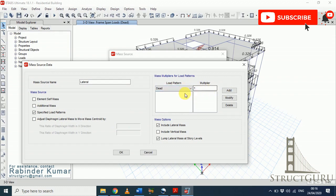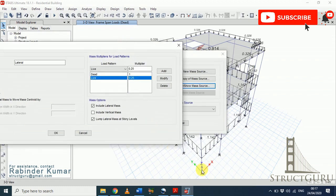So we have to include all the dead loads of the building. Select Dead from this option and click Add, and for 25% of the live load, write 0.25 and click Add. So we are done. Now there are 3 other options, so let me explain them one by one. The first option is include lateral mass. That means the mass in the x direction and y direction will be included. The second option is include vertical mass. This is unchecked by default because the mass in this direction is so negligible that it is not accounted for.